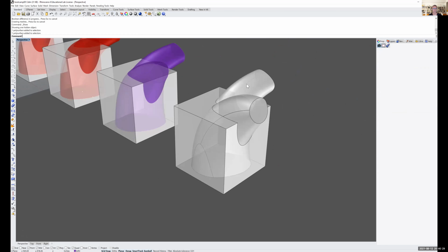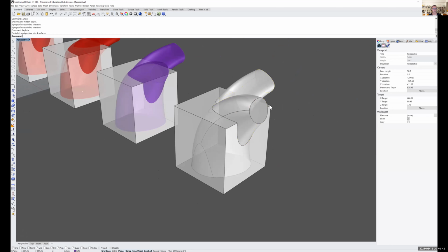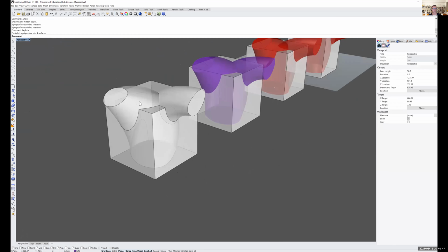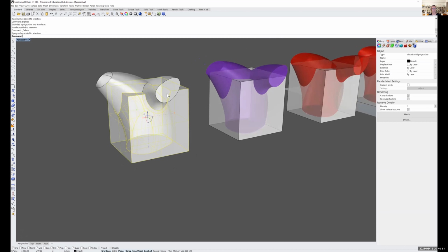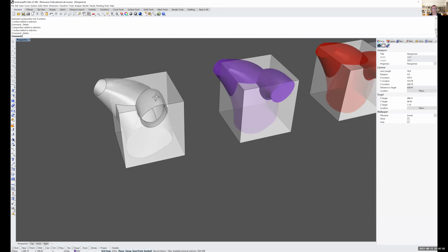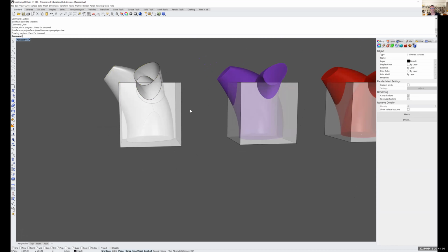And so I'm going to select the vessel that's on the top and I'll explode it. Explode is either the little kind of explosion symbol, middle, halfway down, or you can type explode. What that does is you can see it just turned it into a bunch of individual surfaces, which means that I can select the end caps and delete just those end caps. I can select this and join it back together, but I don't have to necessarily.